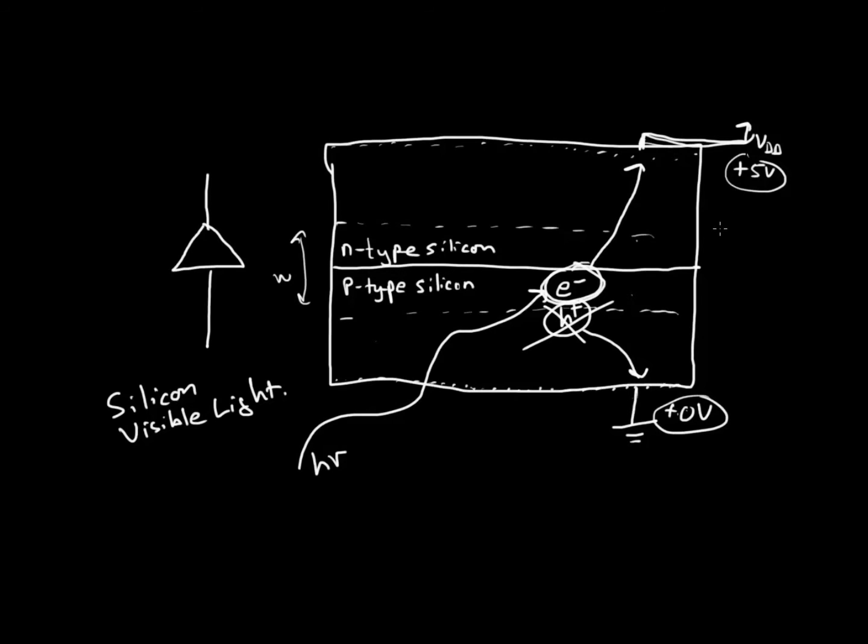Rather, depending on the kind of image sensor you have, you'll either bring that electron out and store it on a capacitor, which will then create a voltage by Q equals CV, and then you'll read that voltage out through some sort of amplifier, or you'll store it in the pixel or jostle it around in the pixel by alternating clock phases, and that'll hopefully become a little more clear later on. But the basic idea is that this electron is going to be attracted towards the most positive potential in the system, and that's where we're going to read that electron out as signal somehow.